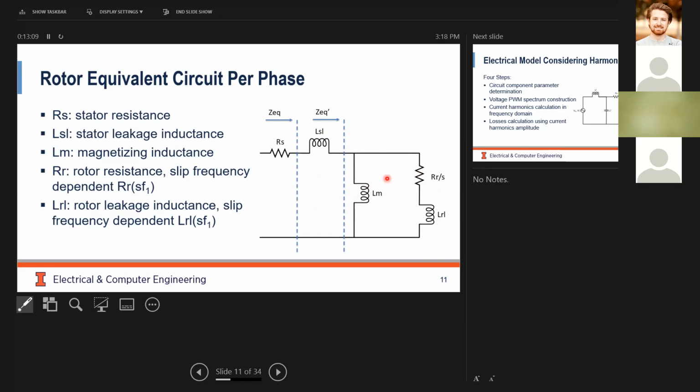Those high frequency currents are asynchronous to the rotor, which means they will induce eddy currents in the permanent magnets, which are a very good conductive material. So that part is like the slip currents or transient currents in traditional wound field synchronous motors.